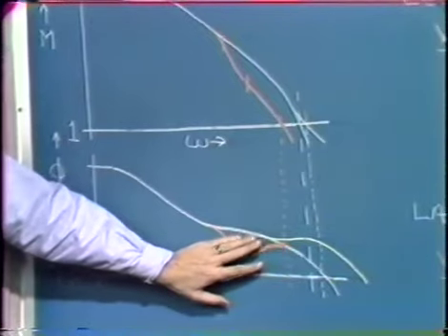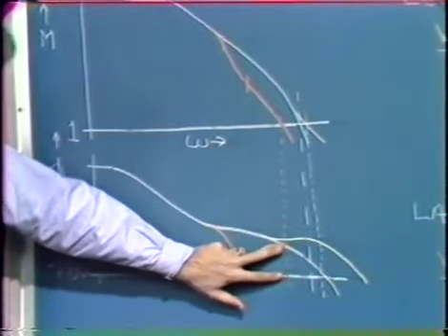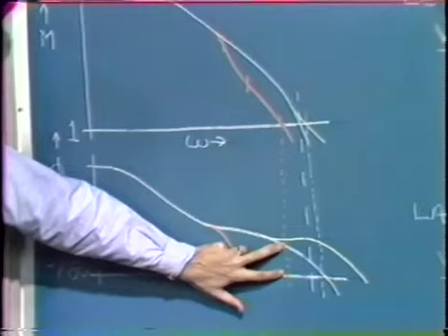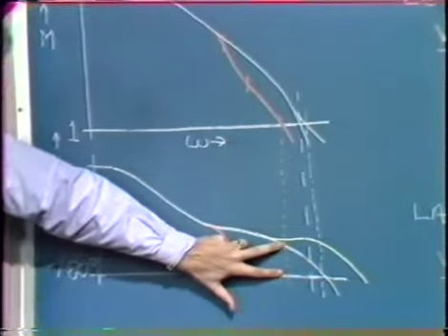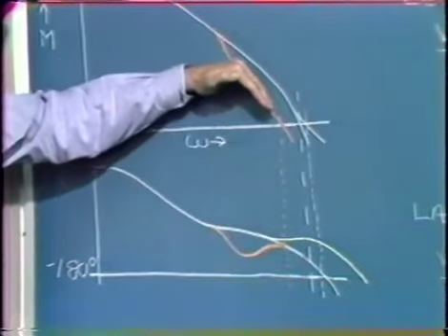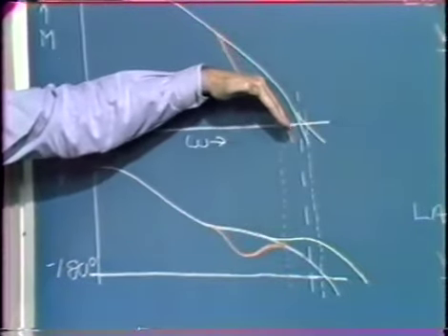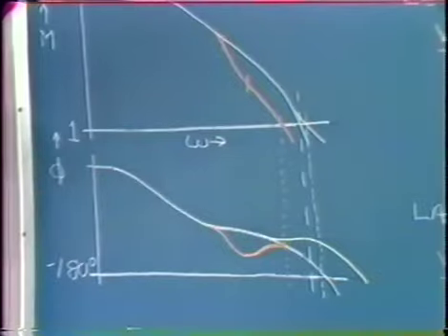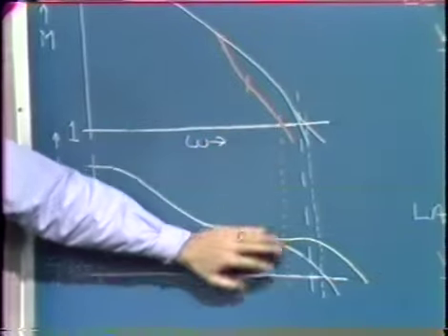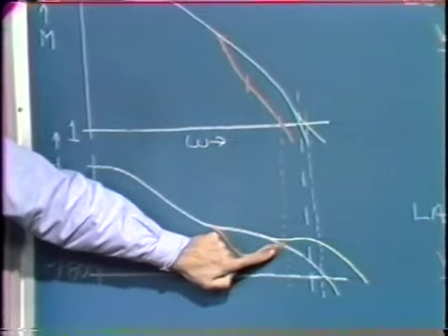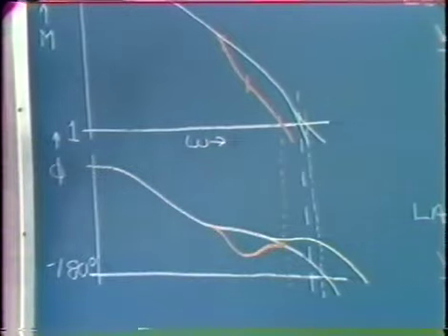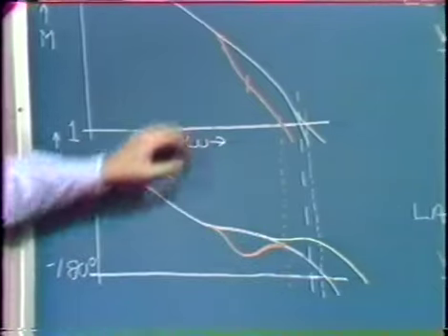And as I've shown in this construction, we end up improving the phase margin of the system from its original uncompensated value to this value by simply pushing down the magnitude curve, causing the crossover frequency to lower, without having, if we've located things properly, a great deal of residual negative phase shift from the lag network. We improve the phase margin of the system in that way.